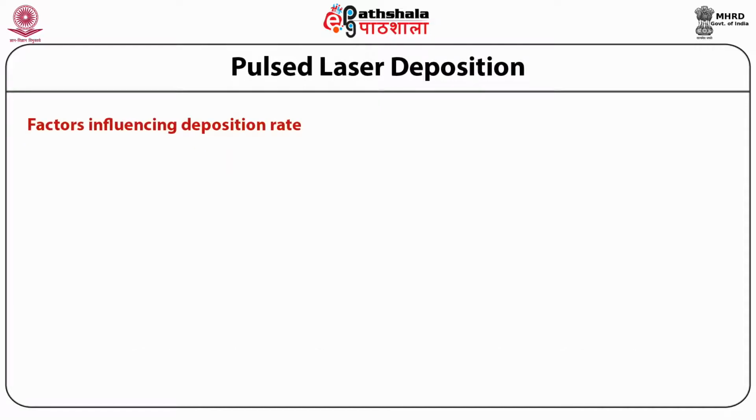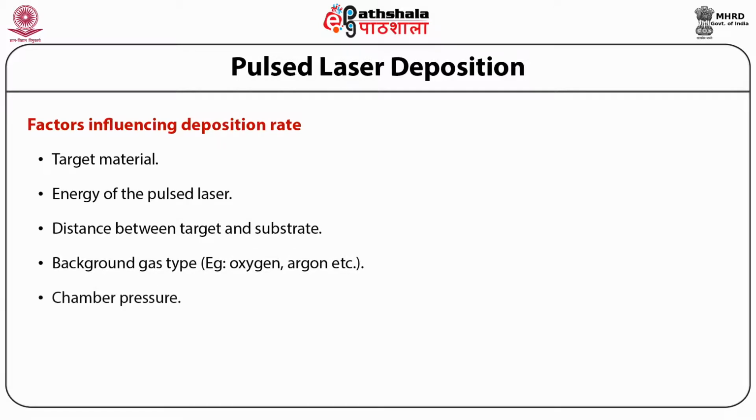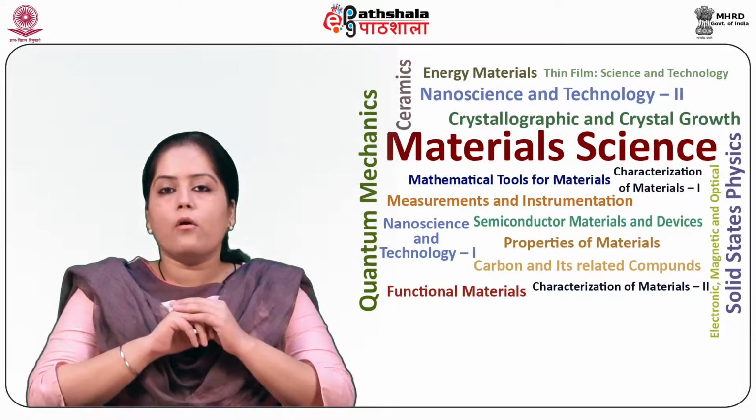There are various factors influencing the deposition rate. These are target material, energy of the pulsed laser, distance between the target and the substrate, background gas type, and lastly, the chamber pressure. Now let us discuss the advantages of PLD.